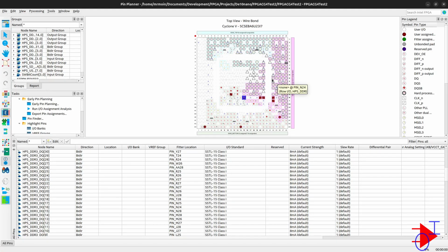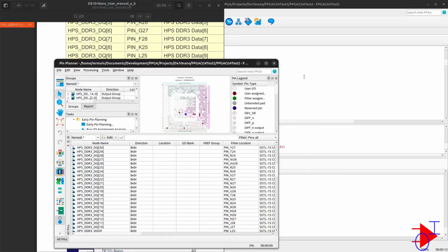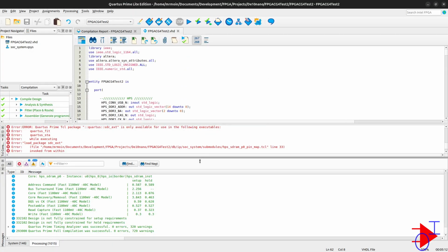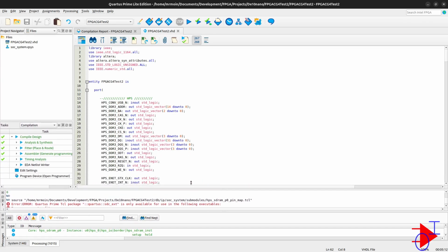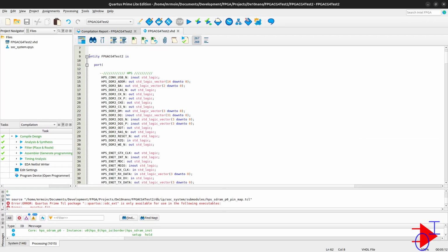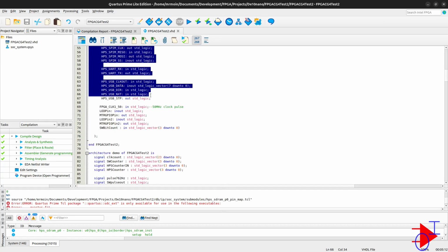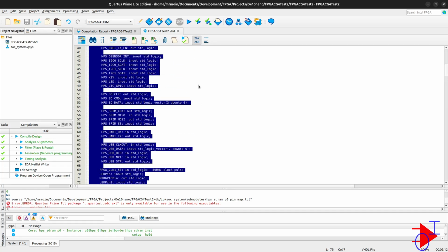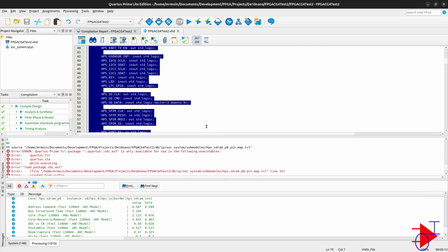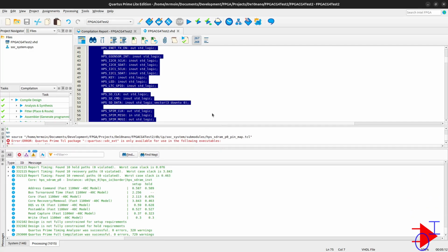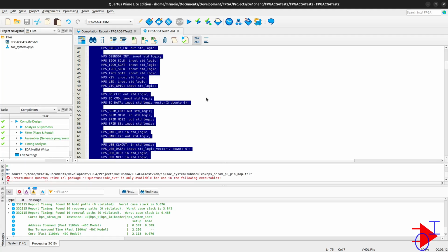The platform designer output, or the connections from the platform designer component within your FPGA code, when it's linked to the port mappings into your top entity up here, the compiler recognizes these connections, and it automatically assigns the correct pin associations.